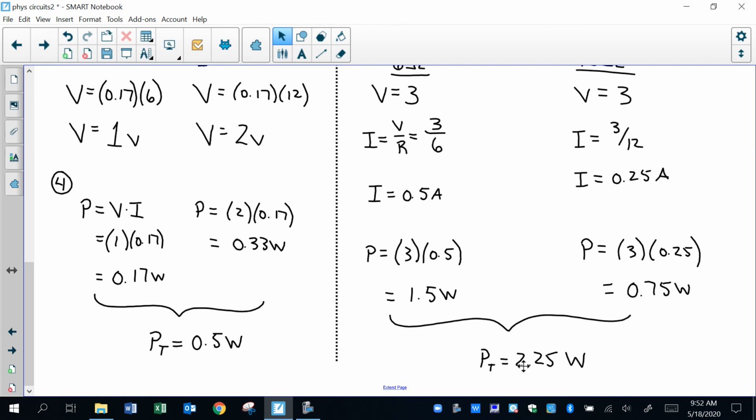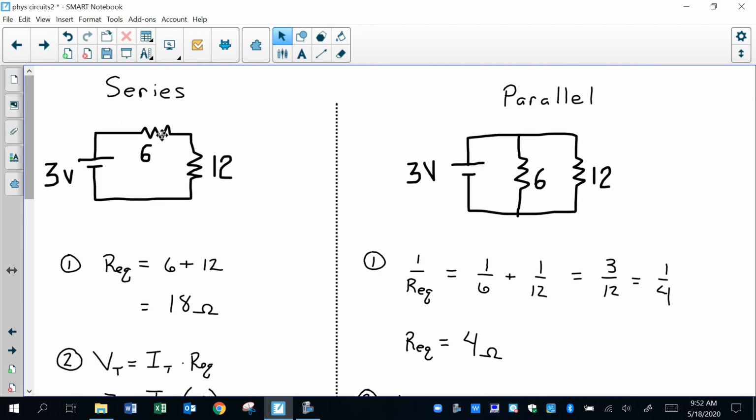And when it comes down here, I can look at this right here and I can figure out my power. Notice how much extra power I get out of this system than this one. And that's another reason why nobody uses a series circuit. Besides being inconvenient, problem with the series, if one goes out, the whole thing fails, right? If I go up to the top here, if this bulb burns out, there's a break in the wire. If there's a break in the wire, the charges cannot flow and everything goes out. So besides that being extremely inconvenient, if this bulb burns out, there's still a path for the 12. So this is how your house is wired. If one thing is broken, gets turned off, bulb goes, whatever, everything in your house keeps working.